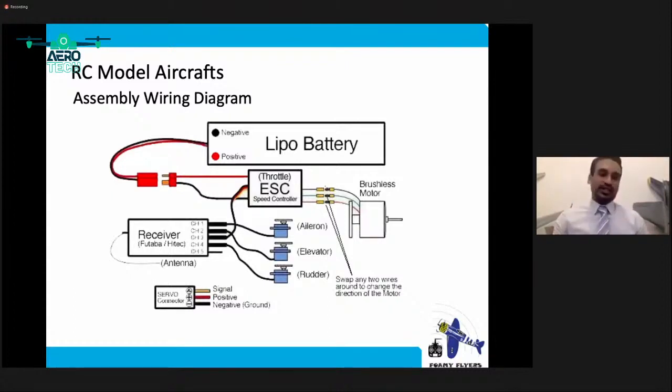And the other thing is, for example, if you have a normal motor, and that particular motor is rotating in a particular direction, if you want to reverse that direction, then you would reverse the polarity of the connectors, right? But in these brushless motors, you have 3 wires. What you need to do is basically disconnect 2 of the connectors, swap them, and then connect them back in again, and then it will rotate in the other direction that you would want. So that is how it is.